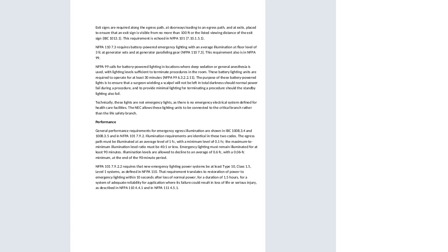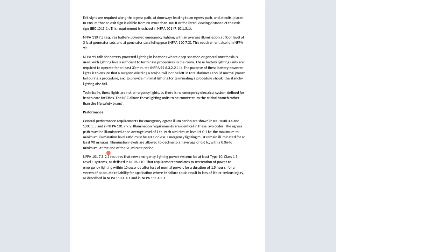Technically, these lights are not emergency lights, as there is no emergency electrical system defined for healthcare facilities. So the NEC, the National Electrical Code now, allows these lighting units to be connected to a critical branch rather than the life-safety branch.